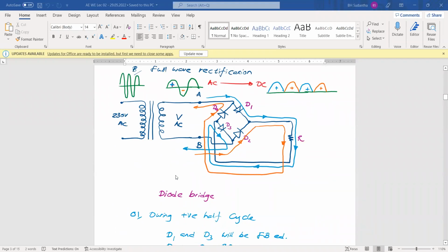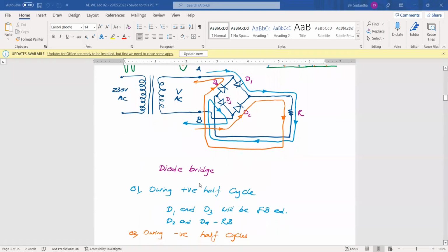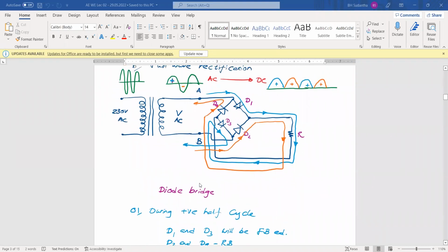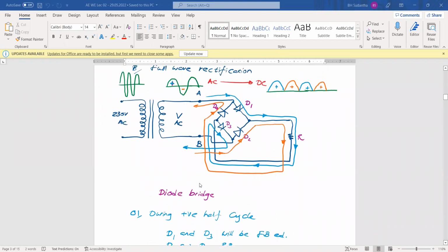We can transfer everything to the other side. But you know that when we transfer the power and waveform to the other side, we have a 0.7 volt drop across each diode. Altogether it may be a 1.4 volt drop at the output side. But if we don't consider that, we can consider it as 100% transfer, because both the negative and positive half cycles are there at the output. Then that loss is not here. The only disadvantage is that we have to use 4 diodes.